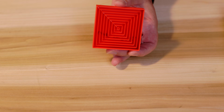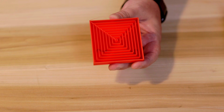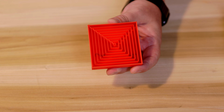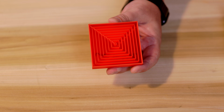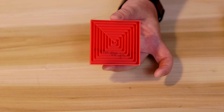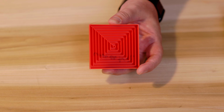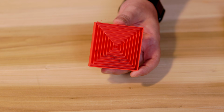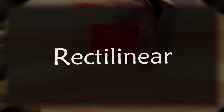The cons of this, it may not offer consistent internal support. Printing tip: ensure your model's geometry is compatible with this infill to avoid potential gaps. Now, the printing time for the full cube for this one would be 1 hour and 6 minutes and using 70.84 grams.